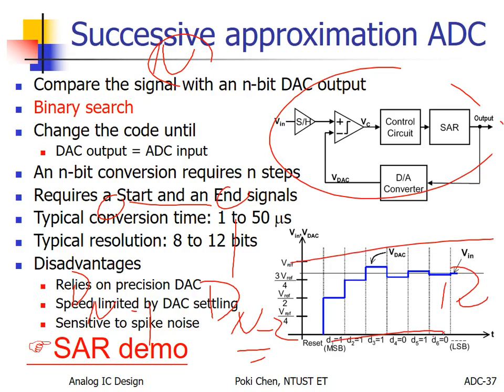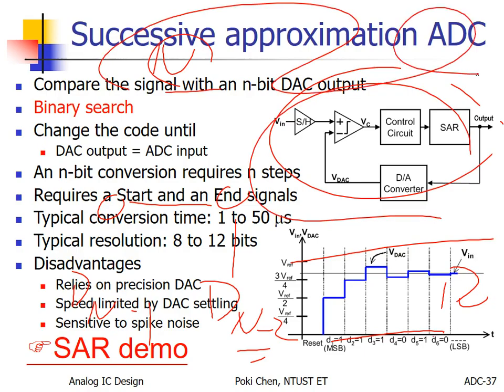So you can see, humankind applies the same idea again and again in different fields. In DAC, we apply this from cyclic operation to pipeline, so we make the cyclic DAC into a pipeline DAC. And here the same. For successive approximation ADC, we use the same hardware to do it from MSB to LSB cyclically.